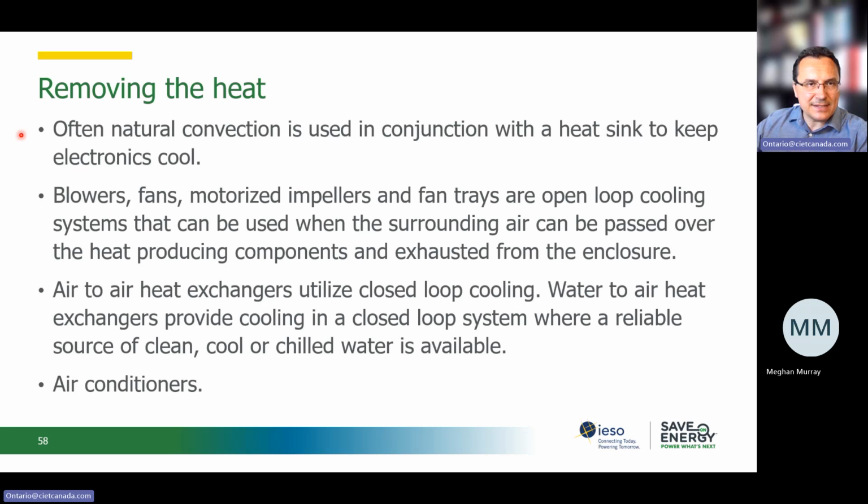As the heat is released, we see the heat being transferred from the high potential, high temperature to a low temperature. So we extract this heat from the equipment, from the electronics to a heatsink, and then that heatsink releases the heat into the space. Warm air will rise and then allow for cooler air to come into the heat exchanger and then extract more heat.